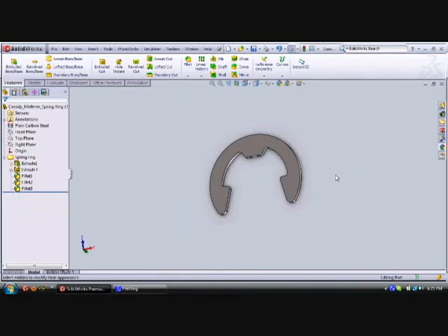Another interesting challenge I faced was the design of this spring ring. Initially, I thought it was just a washer with 90 degrees of it cut out, but when I finally got the cylinder away from it, I realized that there was an interesting configuration and not what I originally thought. This design allows 3 points of it to touch the cylinder, get into that groove, and also allows a machine to just press it on versus having to actually bend it on.